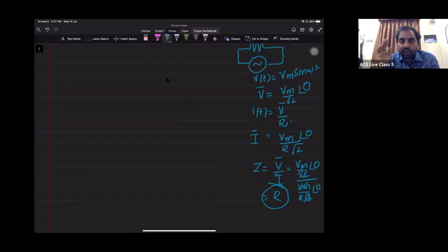That is the reason in all our calculations, whenever you use impedances, the voltages have to be phase and the currents you get will be phase. By definition, impedance is the ratio of phase voltage to phase current. So whenever you calculate current using the impedance of a branch, you need a phase voltage. I hope this point is clear. Confirm me, all of you.